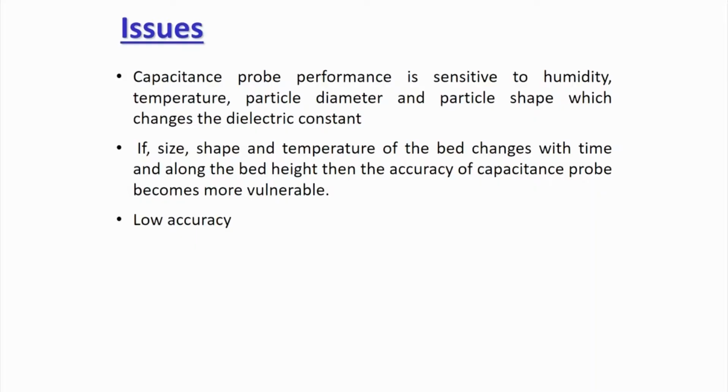Why? Particularly for the needle probe, you are putting in a needle and trying to measure the capacitance across that needle. Now, we know that capacitance will change if you have certain moisture in the bed. So, this capacitance probe performance is very sensitive to humidity, temperature, particle diameter and particle shape, which change the dielectric constant. If you change any of these, your capacitance probe is very sensitive to it.